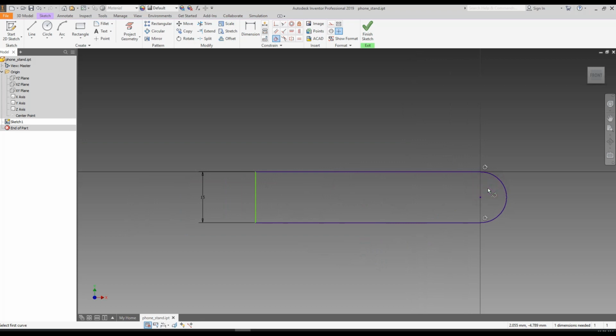So why do you want to do this, you may ask? Why can't we just put in 7.5 millimeters? That seems much easier. Well, there are some really clever things with CAD, and that is that it is parametric. That means that you can have parameters where you change one dimension and other dimensions change with it. So let's try one thing. This is a little bit of a sidetrack, but I think you will enjoy it. So let's press escape to get out of this constraint.